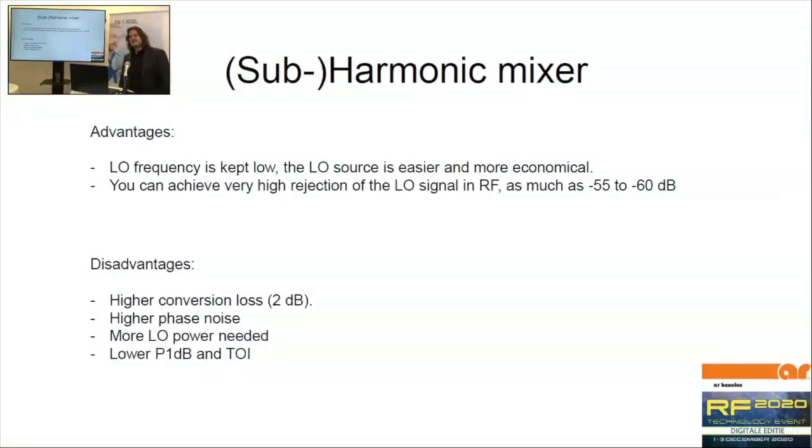So what are the advantages? There are certain advantages to using harmonic mixing. Of course, the fact that you can use a rather cheap local oscillator. That local oscillator usually is depending on the higher frequency, but if you go into the millimeter wave or the high microwave frequencies, the higher the frequency, the more expensive your source will be.